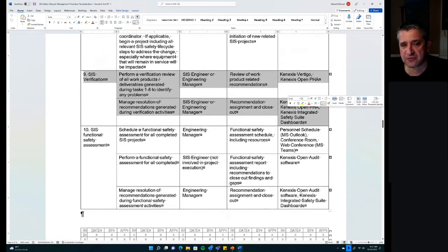Verification is kind of project related. It occurs step by step. There are two concepts in the standard to remember: verification and validation. So validation is your SAT. It's the physical test to make sure that the completed system works. Verification is the step by step, task by task, deliverable by deliverable back checking of drawings and calculations to make sure that they were prepared properly. So this is something that is defined in the corporate standard on an activity by activity basis.